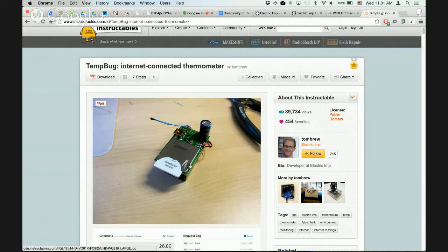But what if I wanted to put 100 of these in a room, like every 2 feet? And what if I wanted to take the data more often than that? I probably don't want to hook up one imp for every 3 or do some crazy huge multiplex thing. What if I want it all to be totally wireless and not too complicated? Bluetooth might be a good fit for that because I can put many Bluetooth devices running on little coin cell batteries that the imp can't run off of because its instantaneous current draw is too high.